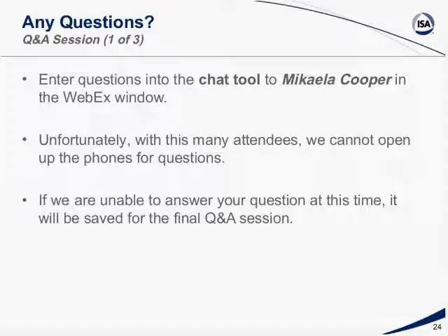If it's a situation where it's only getting active surveillance during a day shift, for example, and after that there is no surveillance, then the alarms that do not shut it down become almost meaningless because there's nobody there to take an action. If I get a high temperature alarm or a high flow alarm that requires an action, but there's nobody there to take an action, it's kind of a meaningless alarm.